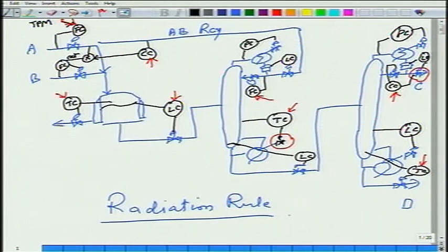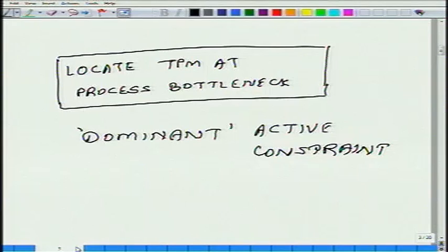If you look at the other two control systems that we drew for on demand production or with boil up in the second column as my throughput manipulator, even in that case, the way I put in the loops, it was ensuring that quality is maintained no matter what. Does that make sense? Does that answer your question? That is a good point, in the sense that quality must always be controlled tightly.